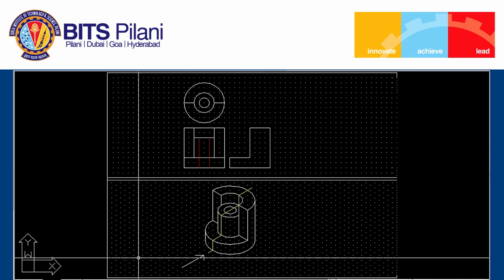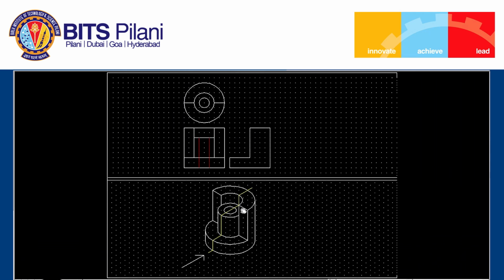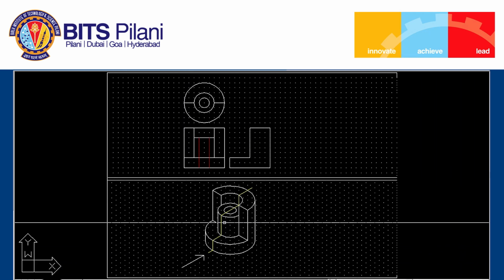So if you see now, this principal surface will fall into a line view, this principal surface falls into a line view, this principal surface falls into line view, and this is the remaining curved surface. Now let us draw this curved surface. So this is the last visible boundary which will fall into a line view, that I can draw here.